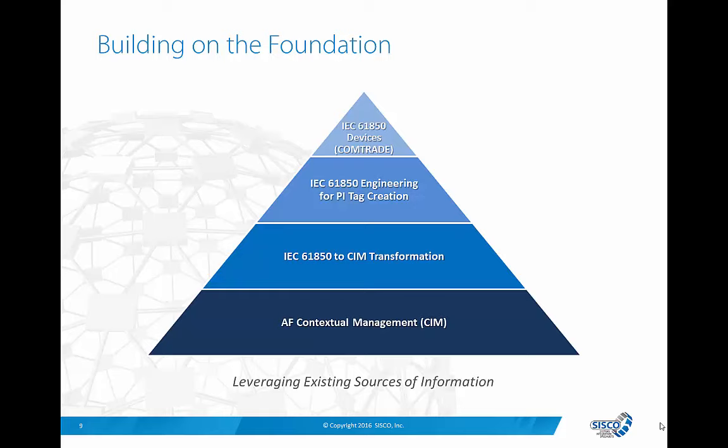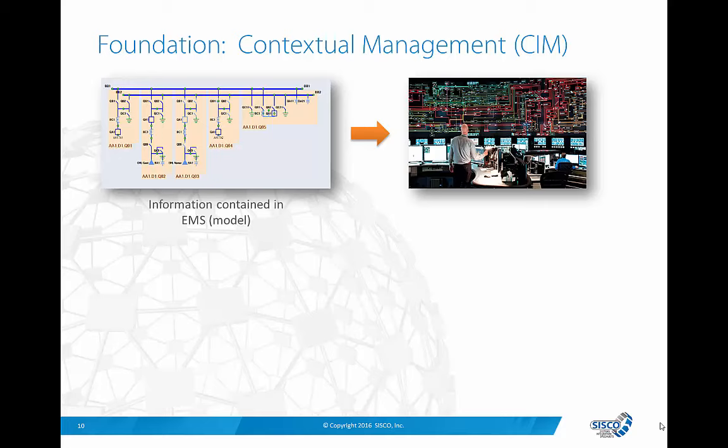And 61850 devices typically have the ability to capture high fidelity information for transient disturbance events that may be of very, very high use for determining if an asset has been impacted by, let's say, a lightning strike.